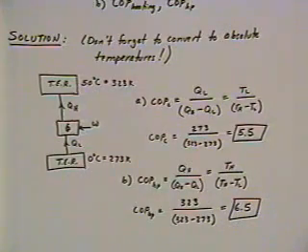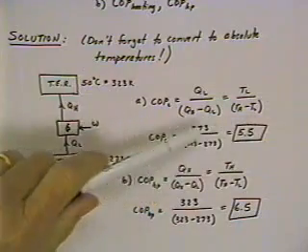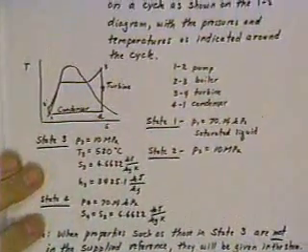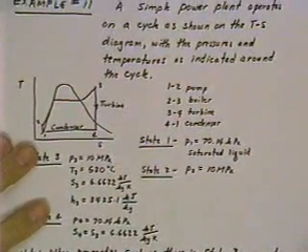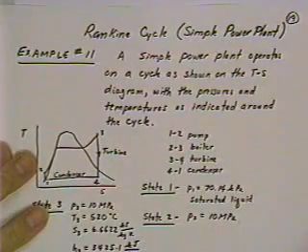You would like for the COP to be as high as possible, because a high COP means that you are delivering heating or cooling at a high efficiency. And so what you'd like to have would be coefficient of performances in the neighborhood of 3 or 4 or 5 or something like this, to ensure that you're delivering the heating or cooling as efficiently as possible. The COP is also related to things like the SEER that you see for air conditioners, but those don't have anything to do with the fundamentals of engineering exam, so we won't go over those.